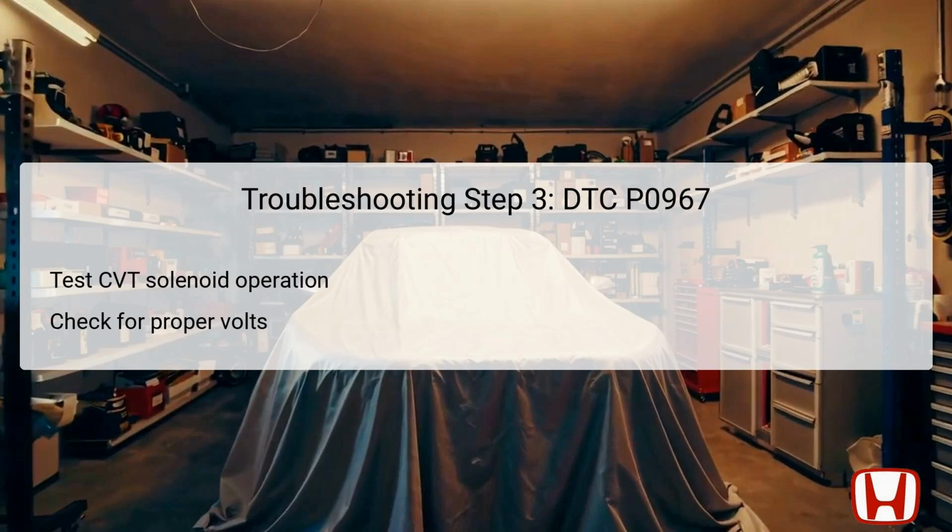If the solenoid is receiving voltage but not responding as intended, it might indicate an internal failure within the solenoid, warranting its replacement. Conversely, if the solenoid is non-responsive due to a lack of voltage, it may suggest an issue with the TCM or the associated wiring harness. This step is critical for isolating the specific nature of the malfunction.